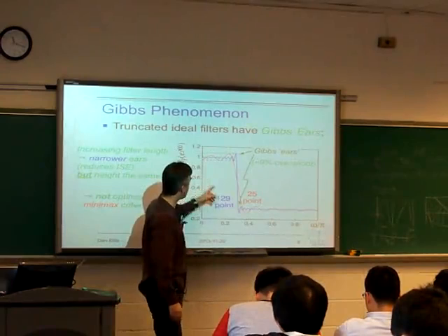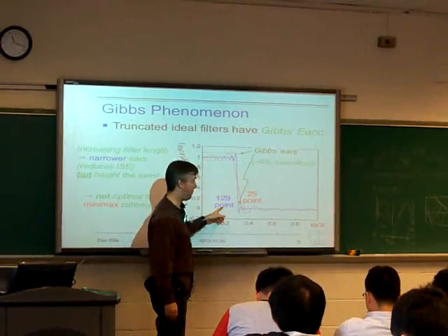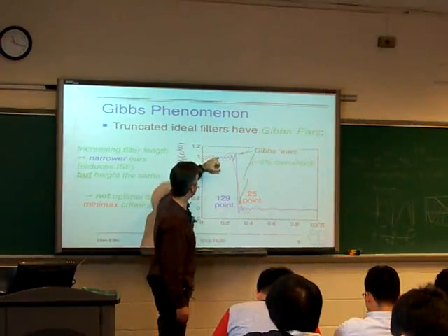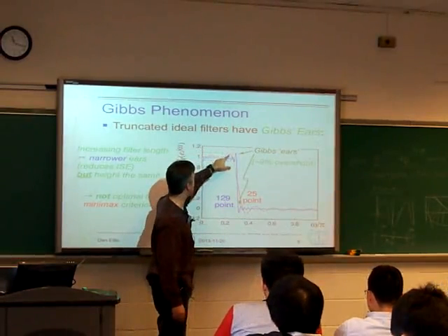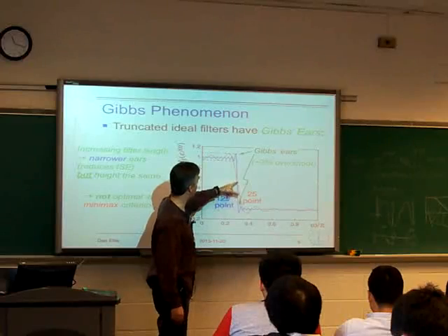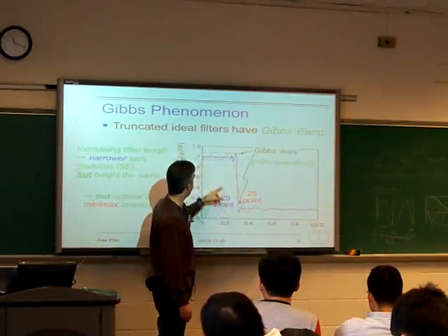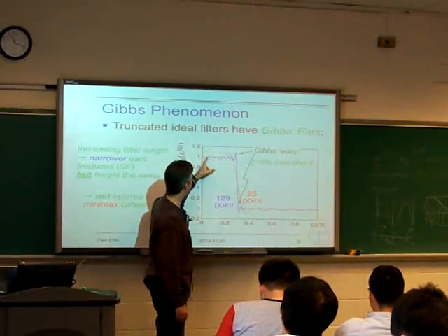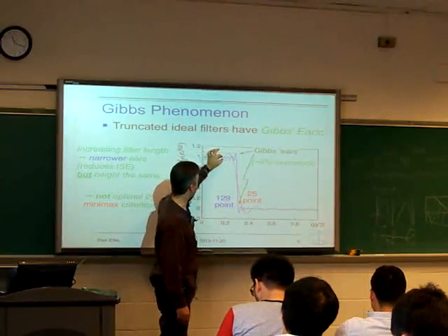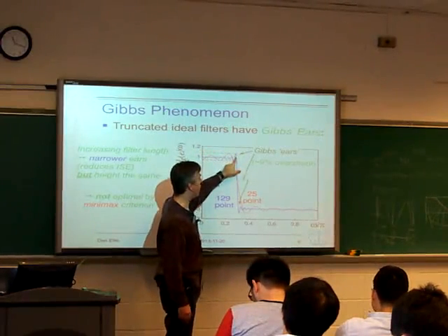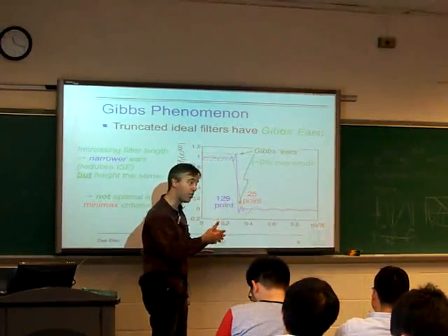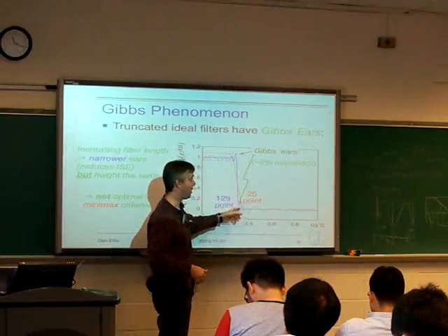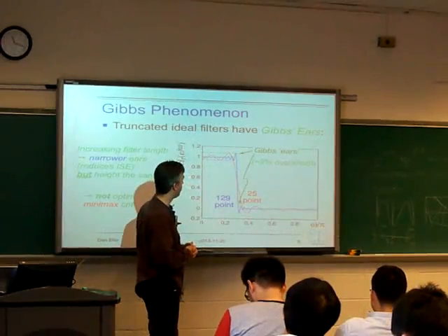You can see that as we go to higher order filters, we get a better approximation. We're trying to minimize the integral squared error, which is the size of these lobes and this triangle of error in here. And you can see that here, there's a lot of error in this lobe. In this higher order one, these ripples are staying smaller magnitude, and there's still this big lobe here, but it's much shorter, so its integral is less. And the blue curve does look closer to being like this rectangular step.